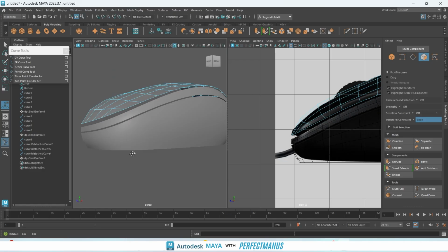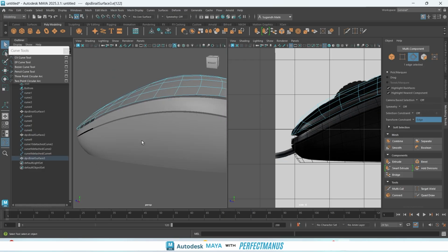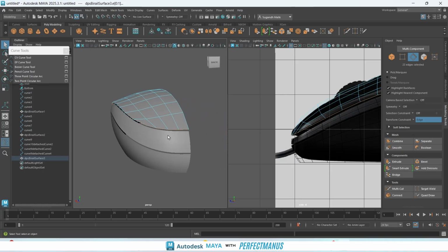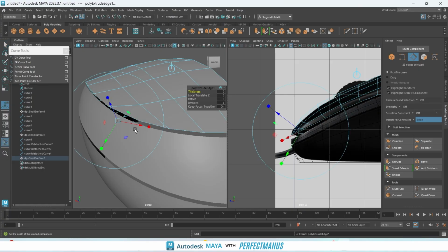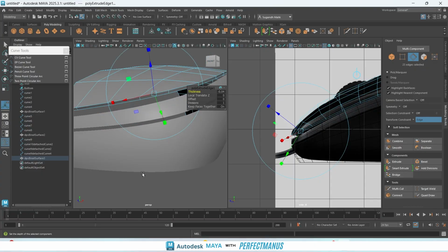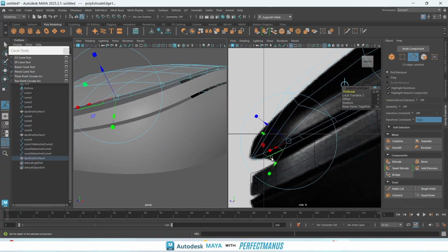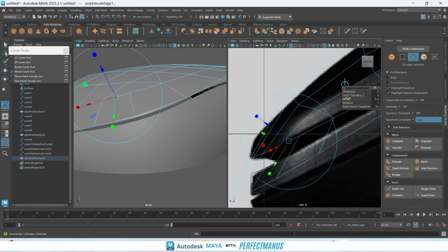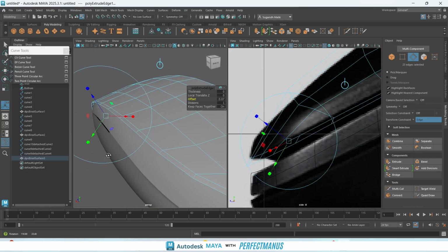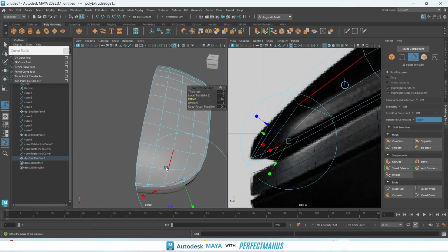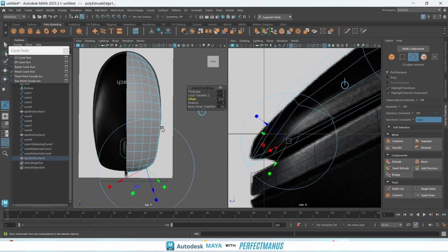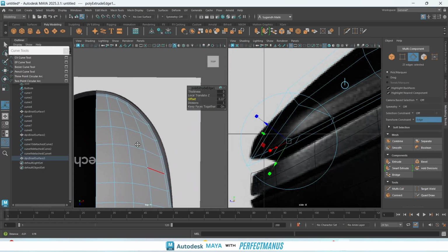So I guess it will be much better for us to just select its edges and extrude them down, because those things will easily be created if you do something like this. Just move them a little bit so that it won't cause any such issues. If we increase this area, it will be spread toward the outside. From the top view we can fix this. See, from the top view we can move our points back.